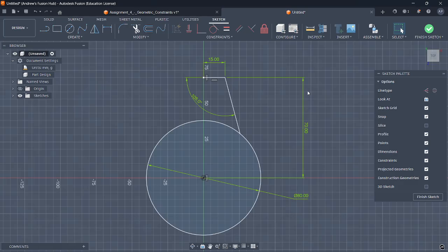Oh, okay. Yeah, one thing to note, sometimes you'll be in one of the constraining tools when you want to drag stuff around. Just remember to hit escape just to make sure you're in the selection tool instead of the constraint tool. Because sometimes I start dragging stuff.